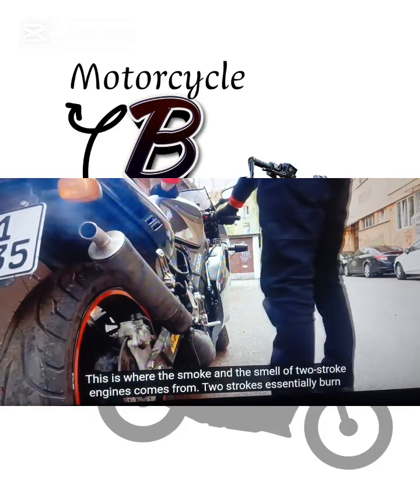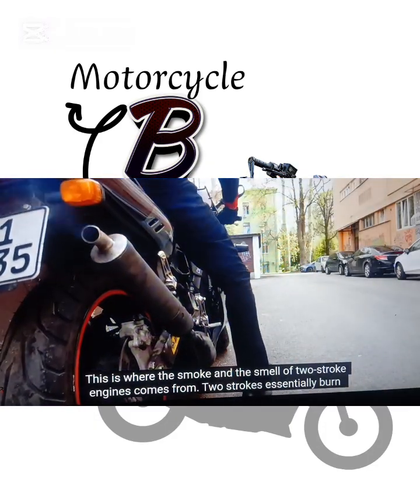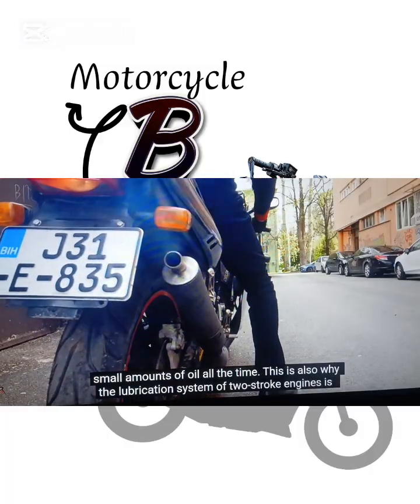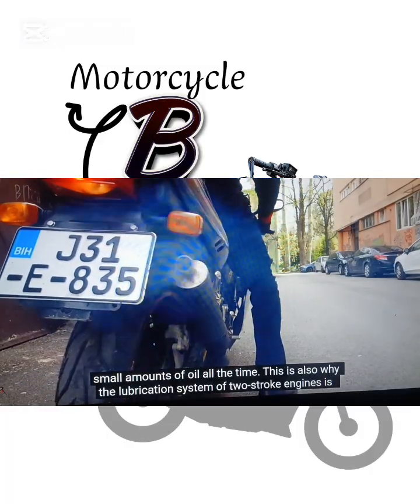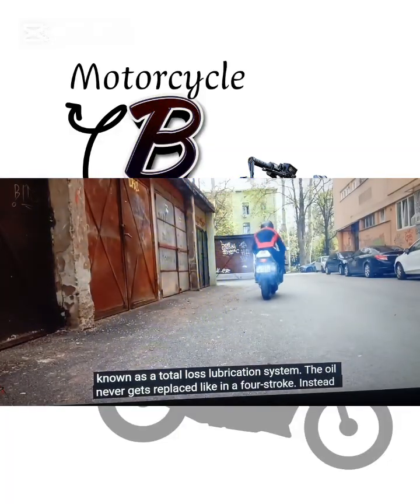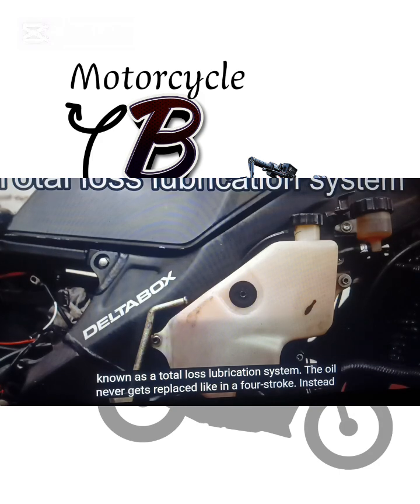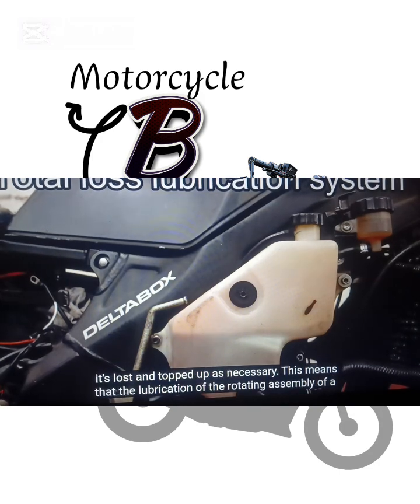This is where the smoke and the smell of two-stroke engines comes from. Two-strokes essentially burn small amounts of oil all the time. This is also why the lubrication system of two-stroke engines is known as a total loss lubrication system. The oil never gets replaced like in a four-stroke. Instead, it's lost and topped up as necessary.